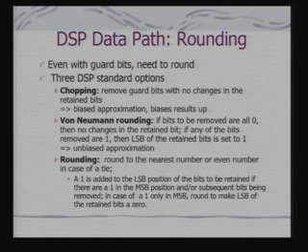Obviously, when we use guard bits, you are increasing the precision. So, when your accumulator is using 40 bits, you are doing accumulate with the help of 8 bits additionally available as guard bits, and your precision increases. But when that result has to be stored in memory, these guard bits have to be discarded because your memory is organized as a 32 bit data word maybe. So, in that case you need to do rounding.